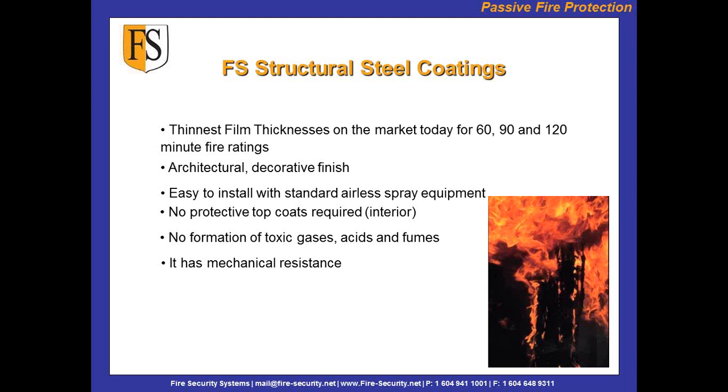So you would spray all of the steel in the shop, then it would be transported to site, then erected after fireproofing's been done, and then an installer would come in and patch up the bolt areas, the plate areas, and the scratch and scuff marks on the fireproofing, and bring it back up to speed. It's still a more cost-effective solution to do it that way than to do it already installed.